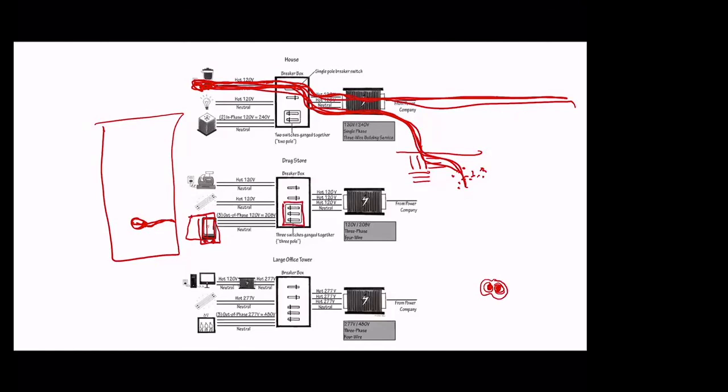But if you're mopping back there, standing in a puddle of water, and you go to move that freezer to get to the door behind it, and by moving it you put your hand on that metal panel on the back of the freezer, especially if you're standing in water, it is going to hold something like 75 times more current than it would take to kill you. So you could very well die from that kind of everyday thing. So what we're going to do is have a fifth wire in there called a ground, and that's going to go back directly to the ground. And the ground, instead of connecting to the motor in the freezer, is just going to connect to some metal portion of the freezer.